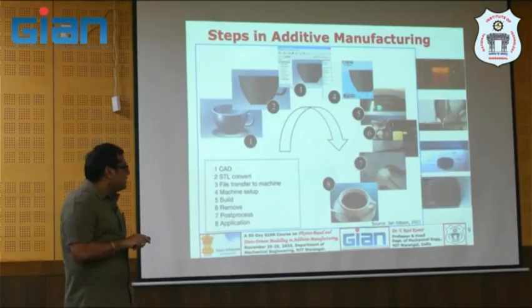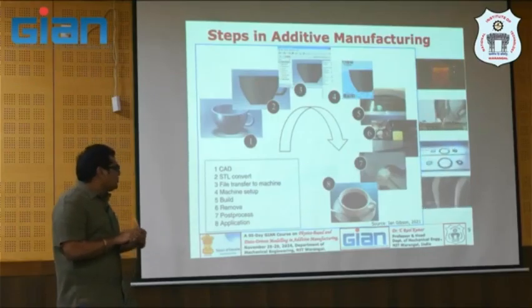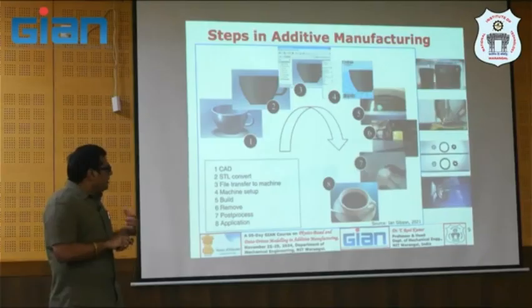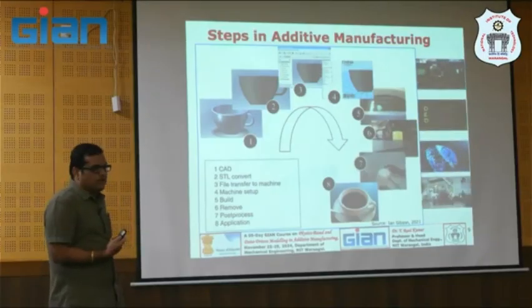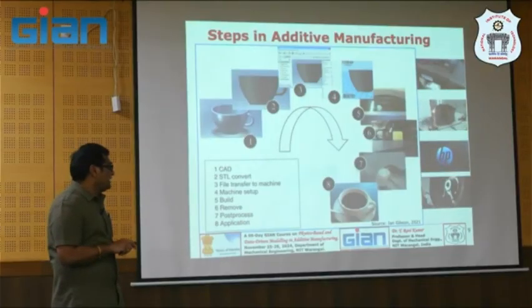And then you unload the part, remove the part. You have the supports, and you have loose powder in case of a powder-based feedstock. So you remove the part, and now you do the post-processing.